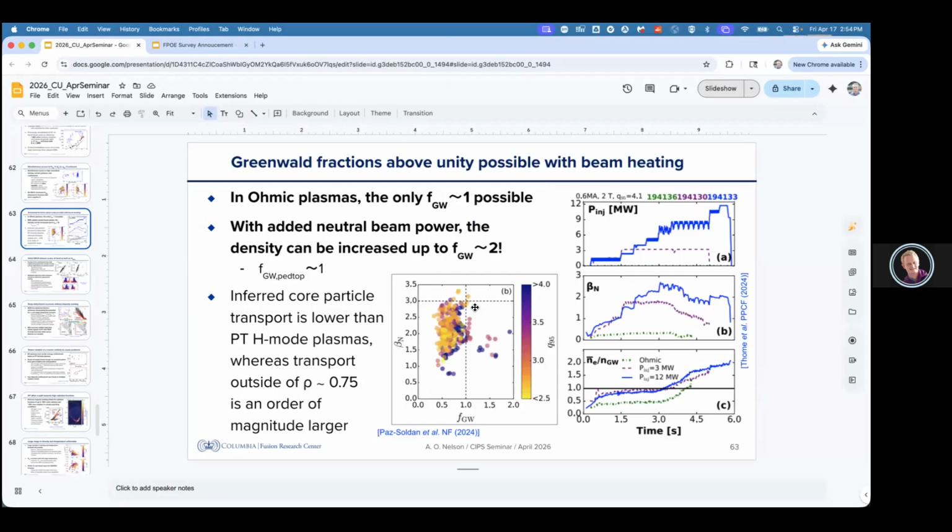There isn't any time to do anything manually, right? You can't say, oh, our density is going too high, and then manually intervene. But you can program a controller to have a limit, and then the controller can look at what's happening in real time and modify something. So shape control is done this way, where we're actually measuring and modifying the plasma in real time. Density control is done separately. We can specify a density target and try to get that density target by puffing in more gas or not.